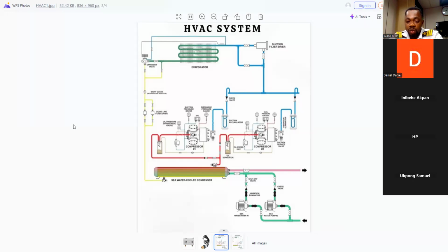It goes back to lubricate the compressor. But on these bigger units, like industrial, they have an oil separator that will separate the oil, and then the oil will go back to your crankcase. In smaller units, there's no oil separator. Okay, thank you, sir. Clear.